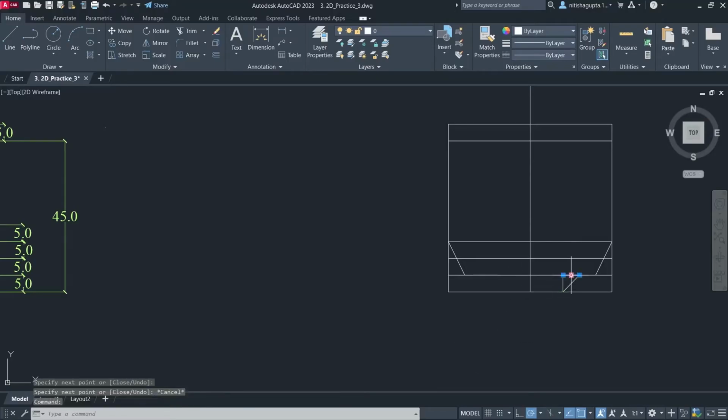We don't need this line, we don't need this line, and we need this line to go mirror on the same on the left side also. So let's take the mirror command, draw perpendicular. We don't want to erase source object. Now let's just trim the outer portions which we don't need. Let's trim these, this and this, and same to the right.